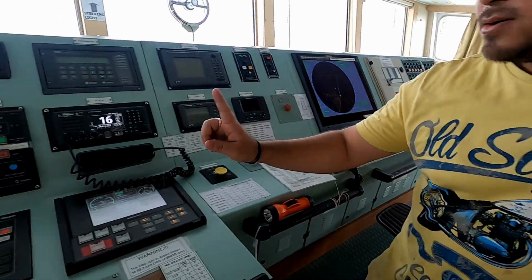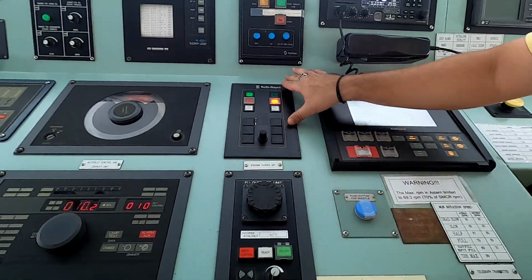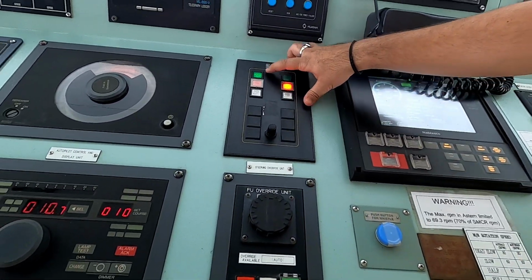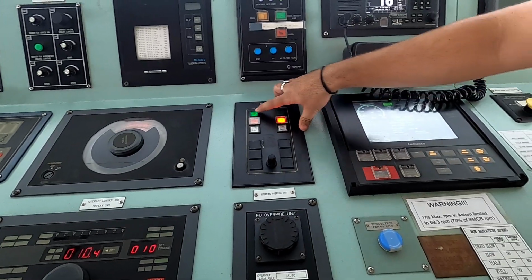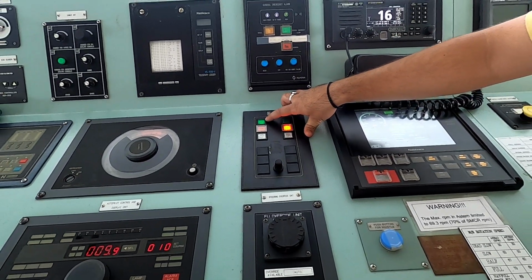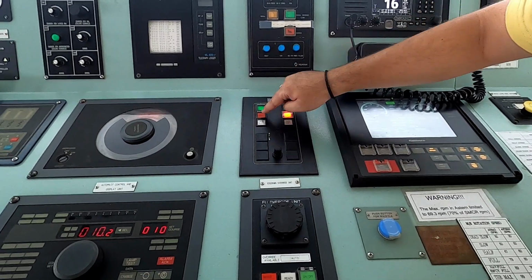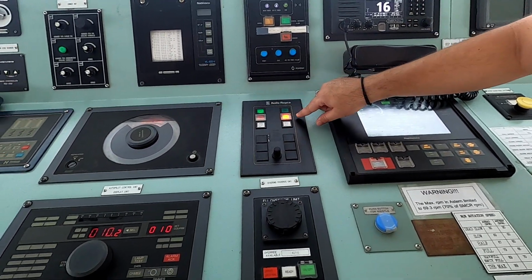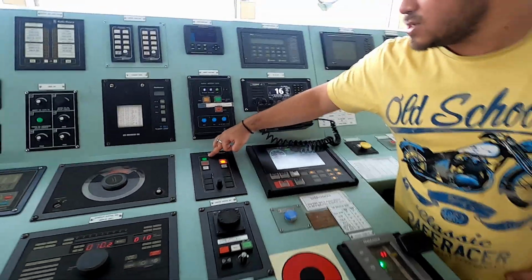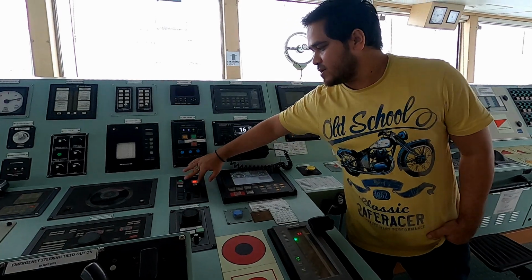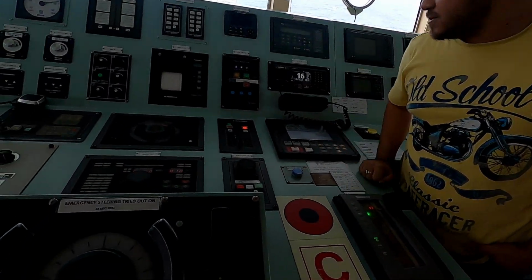And one thing is remaining over here. This is the steering motors. Right now number 1 pump is running. We have 2 steering motors. From this green indication we will come to know this is started. Now pump number 1 is running. To stop it we have to press this button and the indication will come like this. Right now the number 2 is off, number 1 is switched on, and if required we can use both the motors at the same time by switching on the other motors.